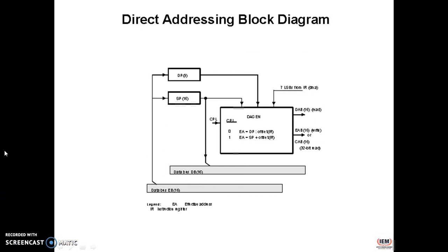The most interesting part, that is the addressing modes. So the direct addressing block diagram is shown here. Their hardware is specifically different from other processors. Here we can see data addressing for the C54 offers 7 basic data addressing modes, like immediate addressing, which uses the instruction to encode a fixed value.